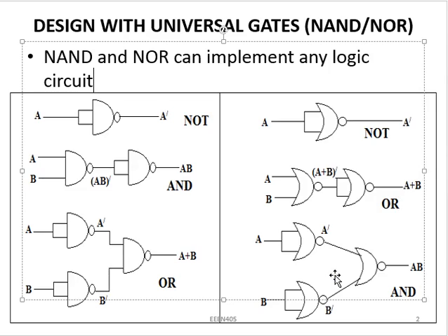And to implement AND gate using NOR, we use 3 NOR gates. The first one takes in A and produces A prime, the second one takes B and produces B prime, and these A prime and B prime will now be delivered to the input of a 2 input NOR gate, and we will have (A prime plus B prime) all prime.